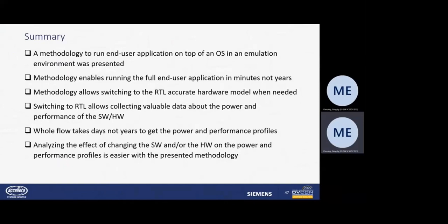We were able to determine the power dissipation for this application running on a real RTL model for the design, using a realistic activity and a realistic specific target technology.